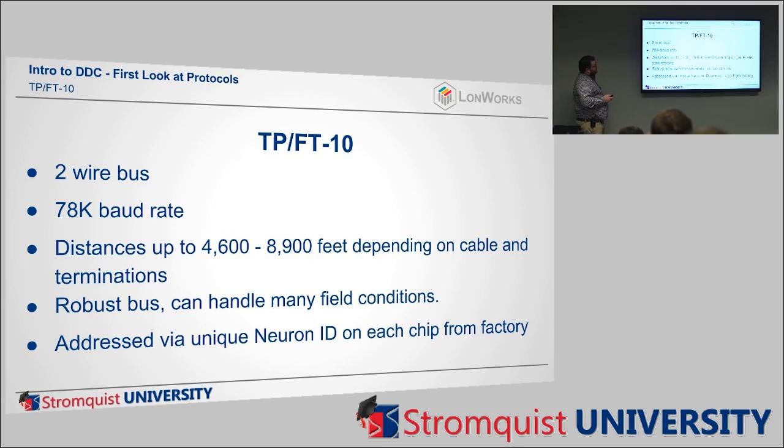And the addressing with LAN, each chip comes burned from the factory with a unique address in it. So there's no setting dip switches out there. There's no having to figure out having 2 things addressed the same. So the advantage of that is less mistakes on addressing and setting something in the wrong dip switch, and you have 2 things fighting on the system.